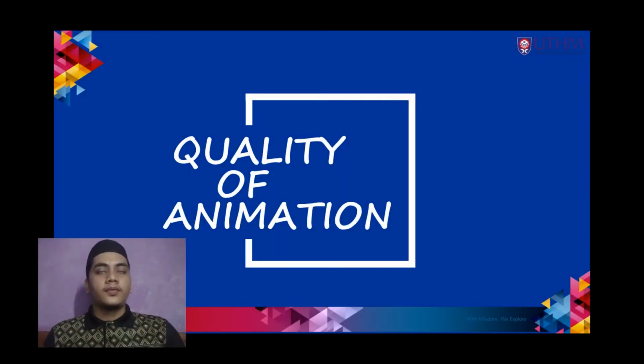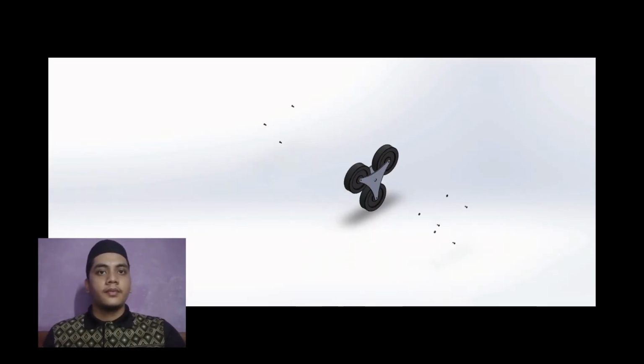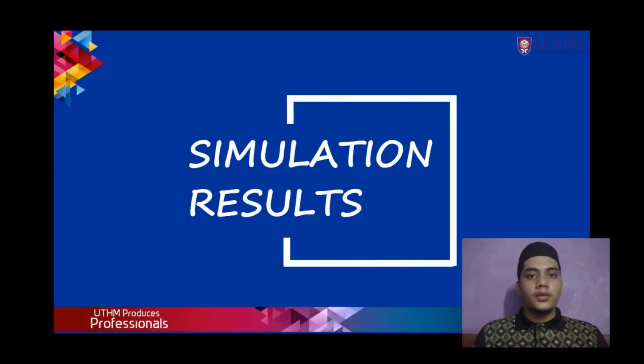For the quality of the animation, the first one is the tri-wheel, and the second one is the box cage. For the simulation results, we use the bottom of the cage because most of the loads will be put on that part. So we picked that part and we get 2 results: von Mises stress analysis and the displacement analysis.